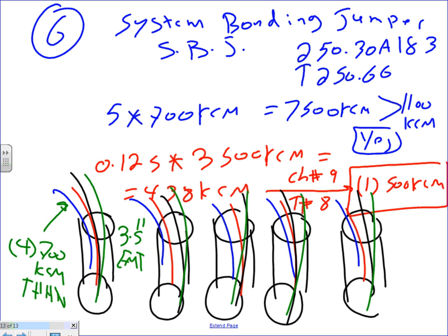And you guys have a picture of it. I have, way at the bottom, if you have a chance, guys, review the bottom one. The bottom tells you the 25-foot tap rule, 25 feet or less tap. That's what we're going to be using tomorrow when we size conductors and overcurrent protection device for a receptacle panel fed from a transformer through a high voltage panel.